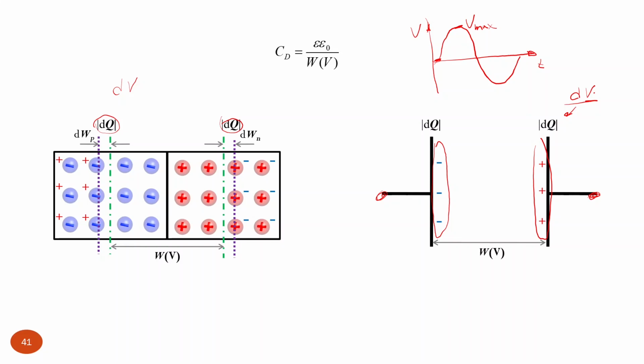That means that at zero potential it was at this position, and at some higher potential, which corresponds to reverse bias polarity, it increased. So the change of this electric charge is also concentrated in a quite narrow layer inside the PN junction, which is defined by the change of the depletion layer thickness in the p-type, and the same should be in the n-type semiconductor in order to have electrical neutrality.